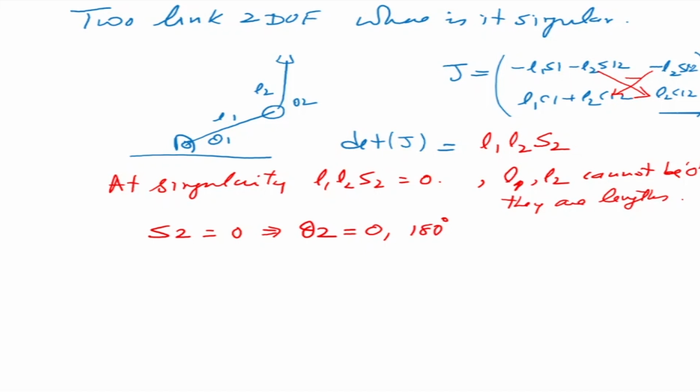So where is 0 and 180? Okay, now something to note is that this is my theta 2, right? So that becomes 0 when the arm is fully stretched, so at that point. And the second is when it is fully folded here. It comes folded, it becomes like this, this side it comes here. That's 180. So 0 degrees and 180 correspond to these positions.